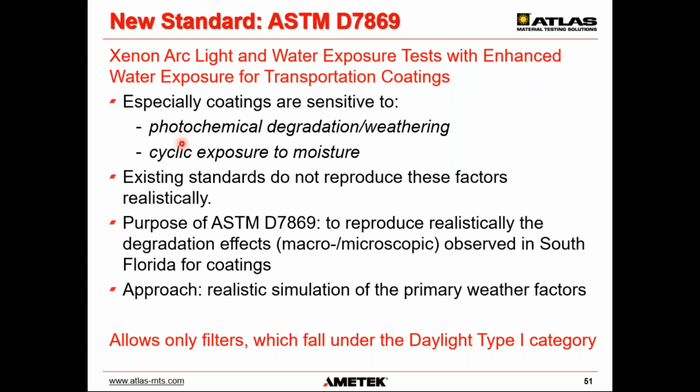And it was found during the development that existing standards did not reproduce these factors realistically. So the purpose of D7869 was to reproduce realistically the degradation effects, both macro and microscopic degradation mechanisms observed in South Florida for coatings, specifically for automotive and eventually aerospace coatings. And the approach was to take a realistic simulation of the primary weathering factors. And it allows only filters which fall under the daylight type 1 category, as I mentioned before.